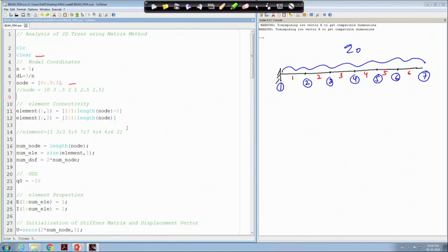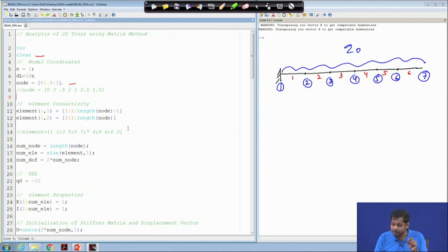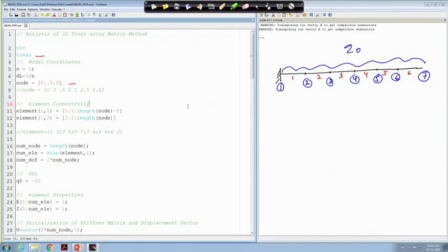Now, the reason why you could draw the deformed shape is that even in one beam, you have several such segments. It is not like the matrix method of analysis, where we had the displacement only at the nodes, at the supports. Here we can divide the beam into as many elements as we want, and with every discretization we get intermediate values of the displacement even in a single member. So, that is how we can draw the deformed shape.